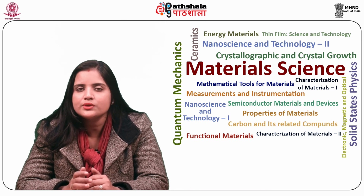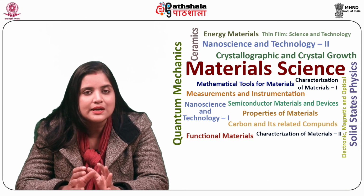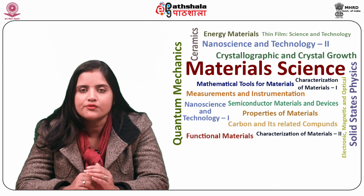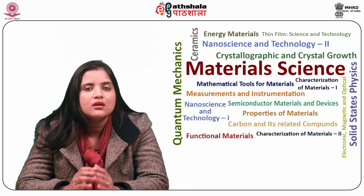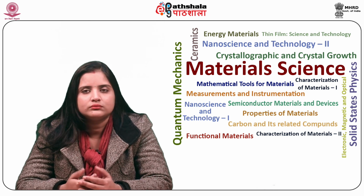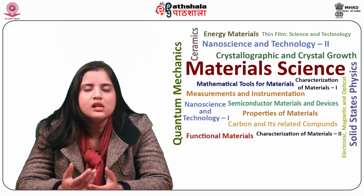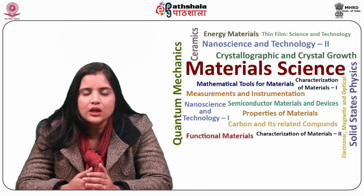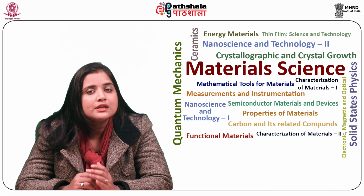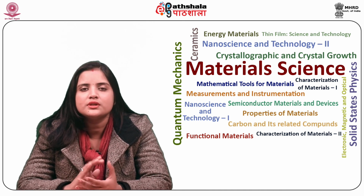It is also used in the semiconductor industry to deposit gold, ceramics, etc. onto a variety of substrates, for example plastic, ceramic, silicon, gallium arsenide, etc. Pre-treatment of the substrate involves mechanical and chemical cleaning and vapor honing for improving film adhesion. Additionally, the reaction chamber must be clean, leakage proof, as well as free from dust and moisture.